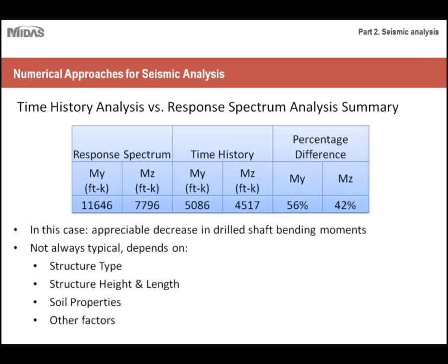So I'll just review that quick point that I made. Essentially, with response spectrum analysis, the results will be more conservative because you're making more assumptions and you're taking fewer variables into account. Whereas with time history analysis, it takes longer to do because the level of analysis is higher. There are more variables taken into account. It's less conservative and it's more optimized. So there's that trade-off. So it really depends, once again, on the type of region you're working in as well as the scope of your project, which type of analysis you would run. But just keep that principle in mind.